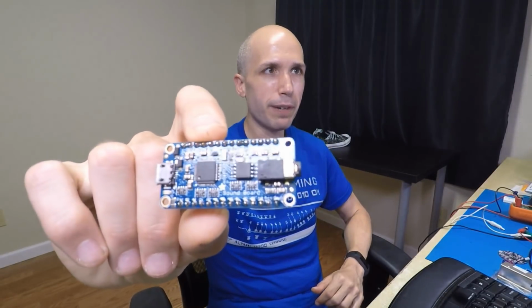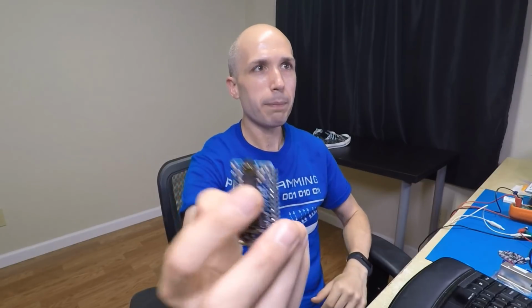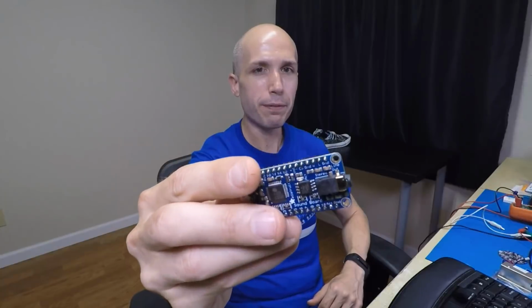But you could have a solenoid connected to it. Another board that I forgot to mention, something like this, is the audio effects board, where basically all of these pins on the outside of this board are inputs. If I connect these to a digital output on my board and set one of these pins to a high logic level, it'll play a WAV file on this board.